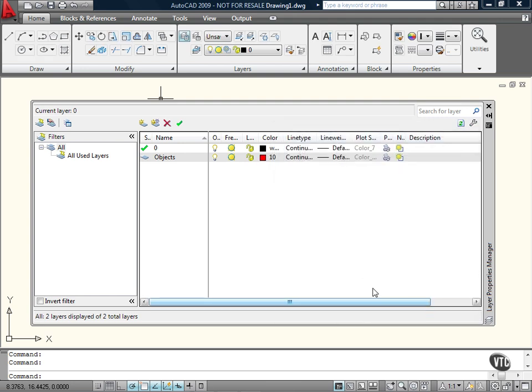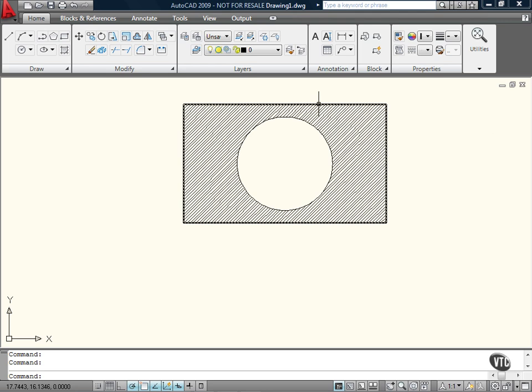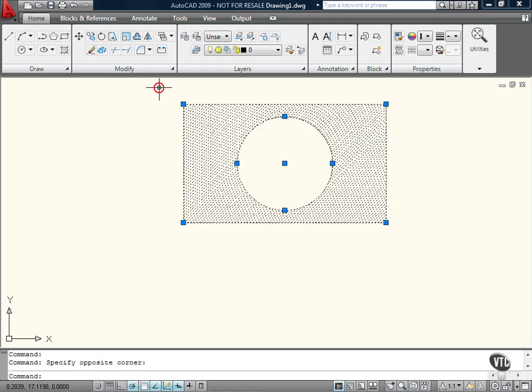When you have thousands of objects on a drawing, these layers allow you to find the appropriate objects that you need to work with. In this case, the objects are going onto the Objects layer, and the colour is red. And on the layer pull down, when you click on the layer Objects, you can directly see the change on the screen.